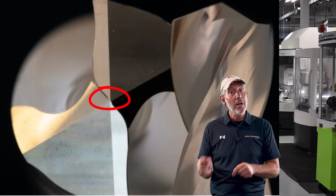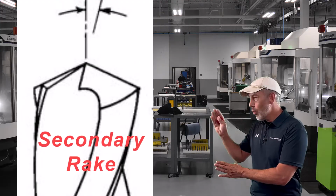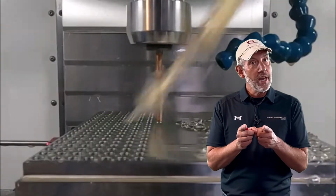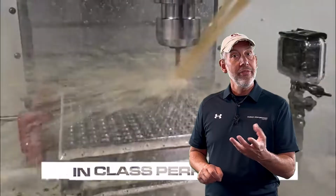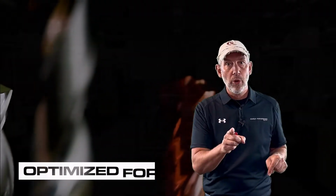Not only are we thinning the web at the end of the drill, but we're also generating more rake on the end of the tool, so it cuts freer toward the center. All little tips and tricks to make a drill cut a little bit better when we do the point geometry. Point geometry is very critical to getting the right tool for the right material. That's why material-specific drills are the way to go when we step into high-performance holes.